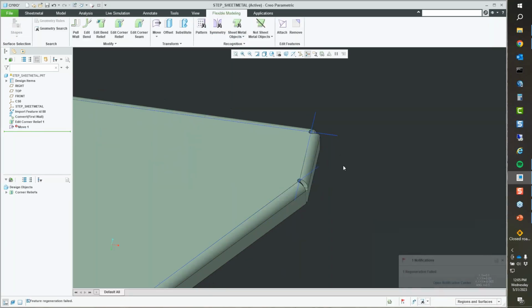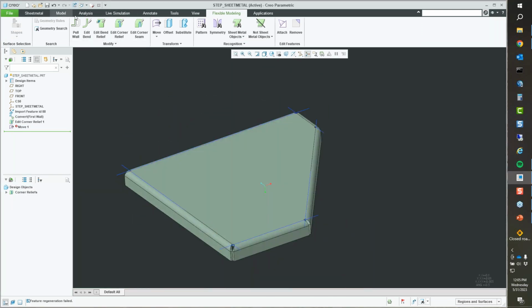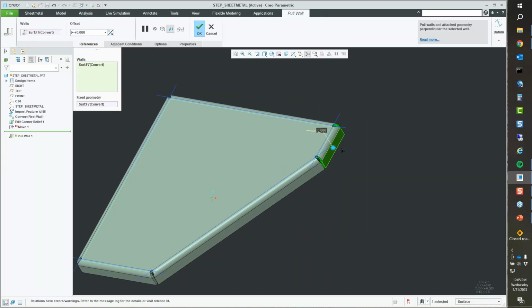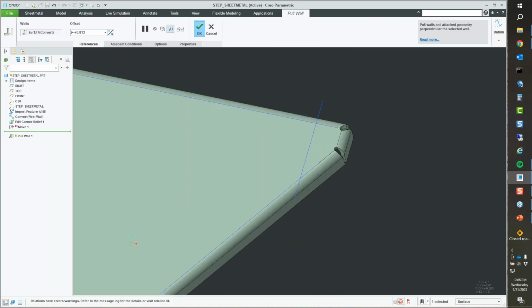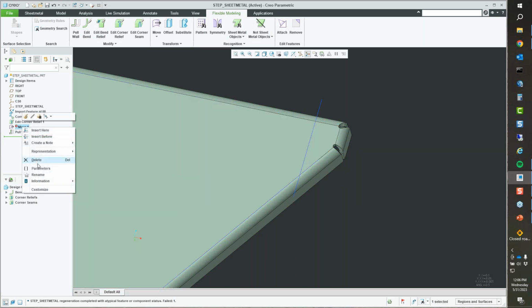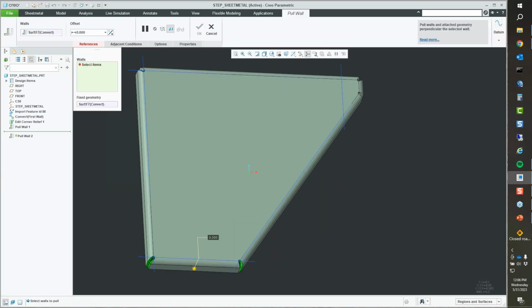No, all right. I wasn't really planning on mucking around too much with the flexible modeling there, but there are a bunch of things. Maybe it was that one. There we go. That's what I was looking to do. So I just had the wrong tool there. In flexible modeling, you have the ability to pull walls. I went a little too far. I failed one of my move tools here, but that's kind of what it's doing. Right? So pull wall is the one I was looking for.